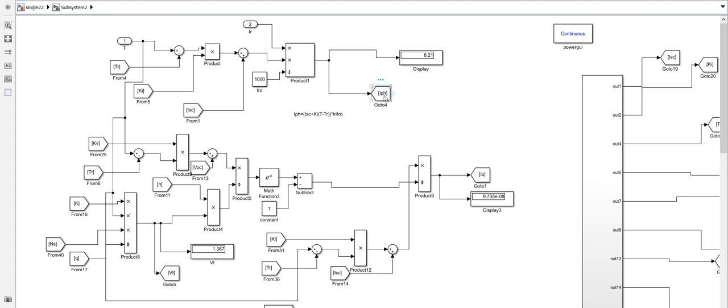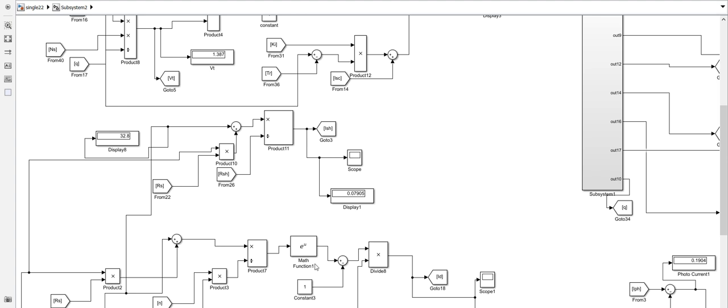Here, I_ph is the photocurrent, and next, I_0 is the saturation current, and the saturation current varies with the cell temperature. Like that, in the improved version, I'm going to use the modified equation, and now with the I_sh current here.